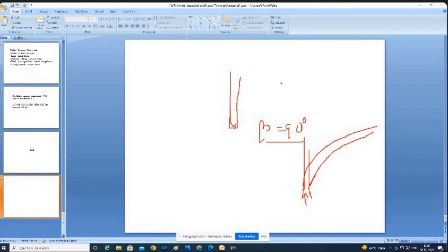That is why sharp flange is not allowed. Sharp flange means the flange thickness is very, very less. Earlier it was like this, and the thickness becomes lesser and lesser, and here it also becomes sharp. So that will lead to derailments in the case of points and crossings.